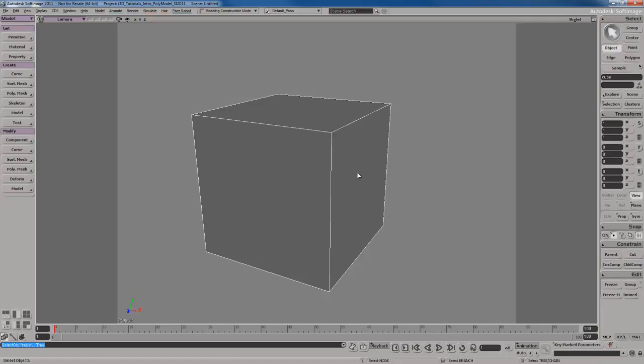Polygon mode is U on the keyboard, to do ray casting mode. If you want to select polygons by dragging a selection, a marquee selection, you can use Y on the keyboard, Y for yellow. That lets you make a selection, and anything that's inside the selection gets selected. Of course, the polygon has to be completely encompassed by my blue marquee selection window. If I keep talking about it, it won't make much sense. What you need to do is take a moment to use these different keyboard shortcuts and get a little bit of experience, get a feel for it, and it'll make sense to you in no time. In just a couple of minutes you'll be grabbing and moving these components around.